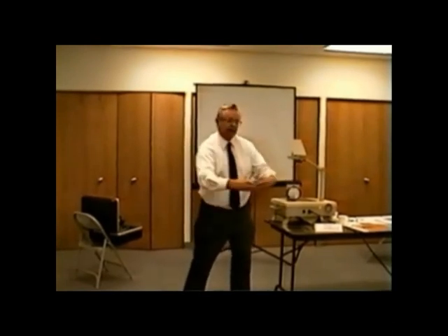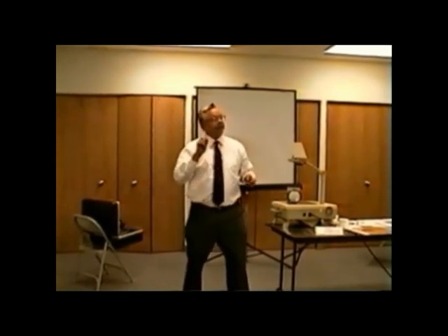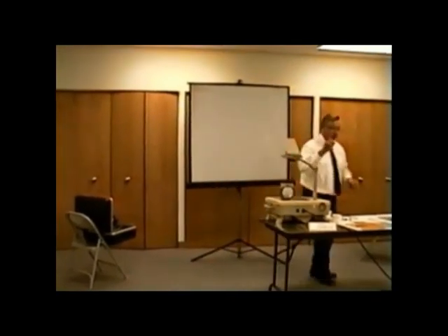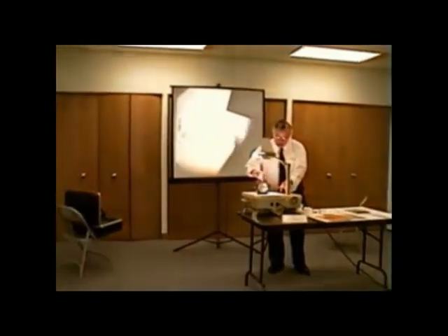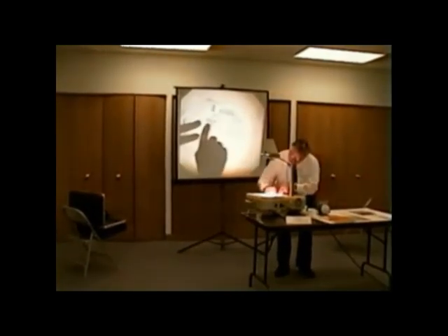Now, the same thing on the return. If we are sucking air, it's negative, and it's also producing pressure on the ductwork, but it's producing negative. That's why when we oil can ductwork, when we blow in the supply, the oil can's outward, and on the return, it'll oil can inward. Okay? So positive and negative. But what are we still talking about? We're talking about static pressure on the ductwork. It's external static pressure. Let me make sure this is clear so you understand. This data tag said maximum external static pressure. Okay, let me shut this off.